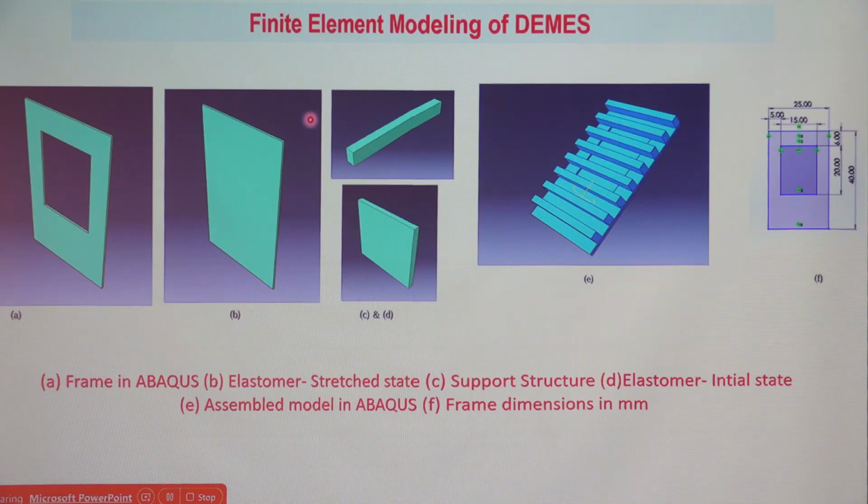In the output you can request the stresses, deformation, strain, everything you want. The initial condition of the stresses behaves like a pre-stretch to the membrane, and when you release it, it deforms the entire configuration to the required bending configuration. You're getting my point? So you see how smartly we have done it. We follow the same methodology that we used experimentally.